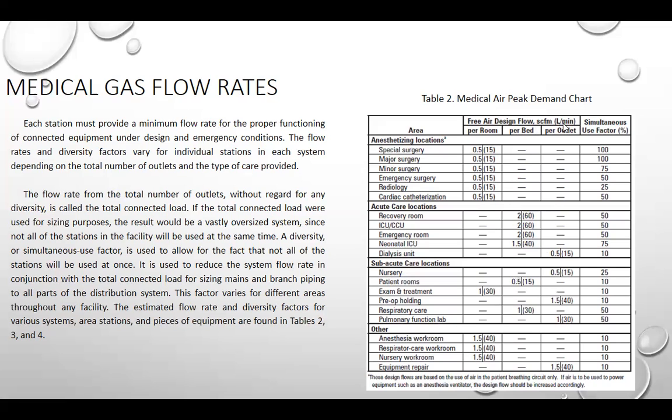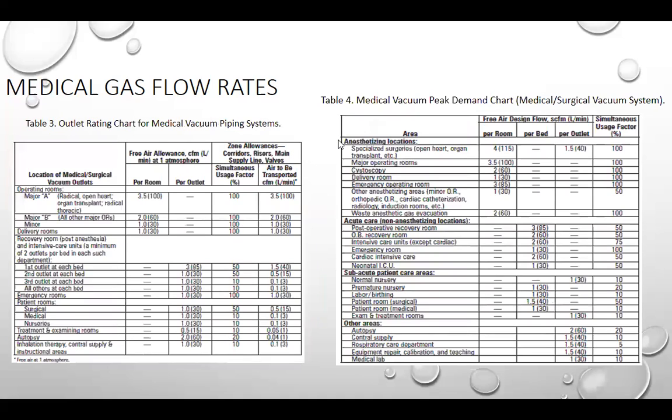You know this SCFM, right? Standard cubic feet per minute based on standard atmosphere condition. Okay? This is different from actual. The actual depends on the pressure, so your flow rate will differ. It's just the ideal gas. So, there, 0.5, 0.5. So, we use this in sizing the compressor. Okay, we didn't explain everything one by one. Level 3, you know how to read, right?